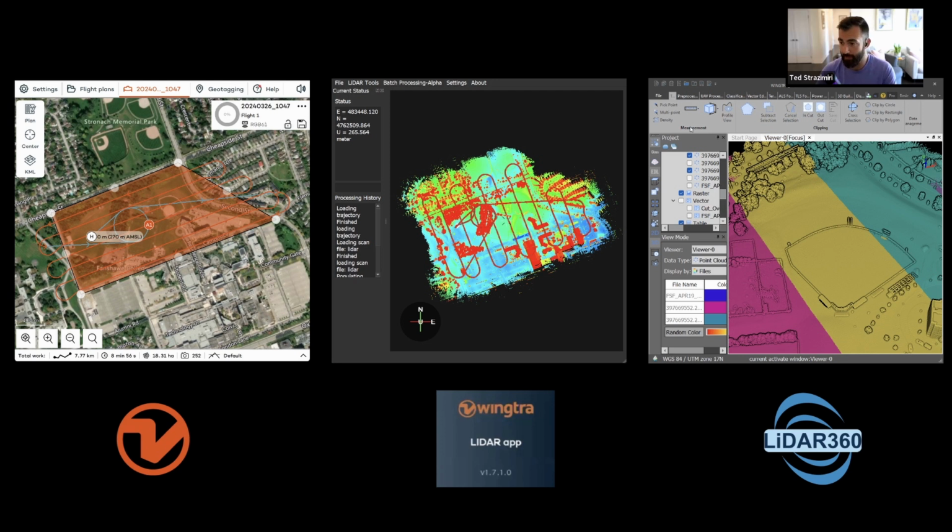That was about twice as long. So in terms of efficiency, that overlap is one of the main reasons why you're able to complete things so quickly. And so that planning begins for me, and sort of the way that I use the Wingtra, and the workflow that I had was to plan on my desktop in the Wingtra Pilot app, and then take that mission, put it into the controller, and then from there fly the mission.